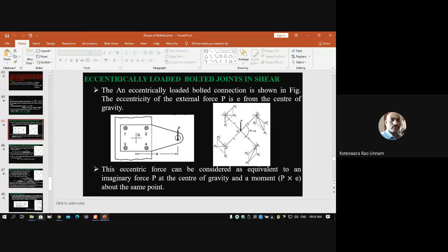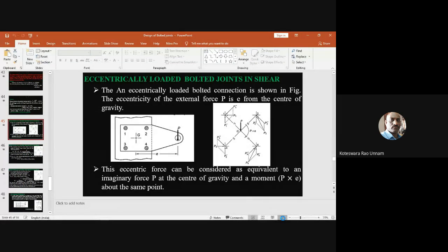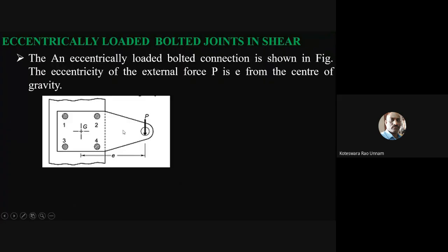Sir. Tell me what is the direction of movement here? Let us say if I take this one as the y-axis, this load is acting along the y-axis. This is the x-axis and this is the y-axis. Your load is in the negative y direction and this offset distance is along the x-axis. So what is the component of moment you are going to get, about the x-axis, y-axis or z-axis?